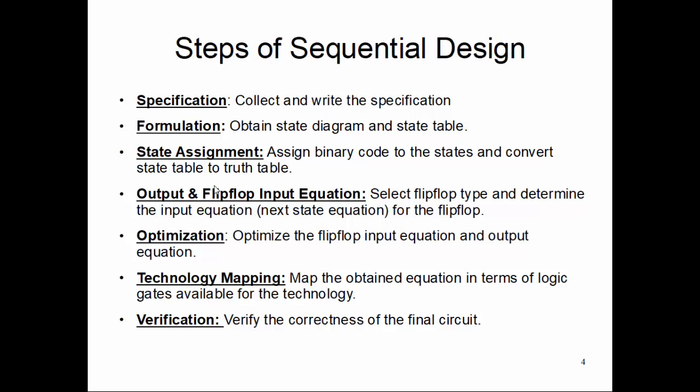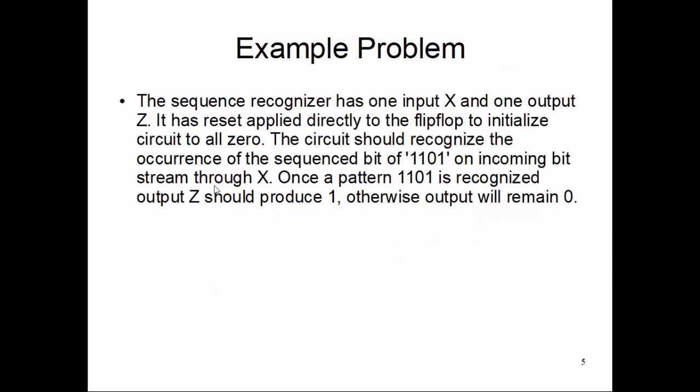Now let's take an example. Let's build a sequence recognizer with one input, let's mark it X, and one output, let's call it Z, and it has a reset applied directly to the flip-flops to initialize the circuit to all zeros, so we can reset the flops.